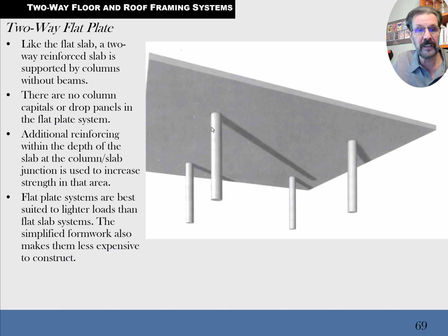And this one doesn't have anything. It doesn't have a drop panel, doesn't have a mushroom capital. So you wouldn't use something like this design probably to build a parking structure. But you might be able to get away with using this for slabs that are supporting condominiums where it's just people inside.